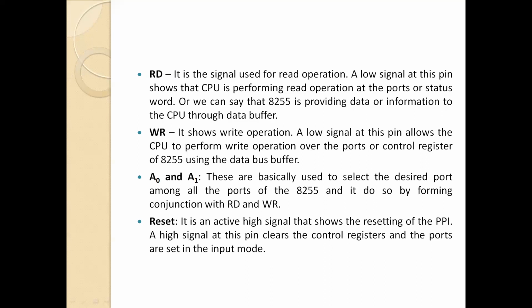Then there is the write pin, which shows the write operation. A low signal at this pin allows the CPU to perform a write operation over the ports or control register of the 8255 using the data bus buffer.